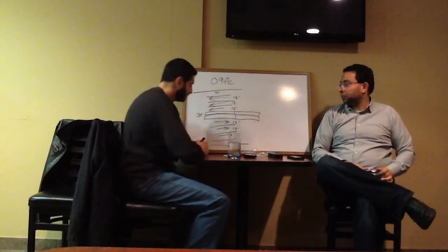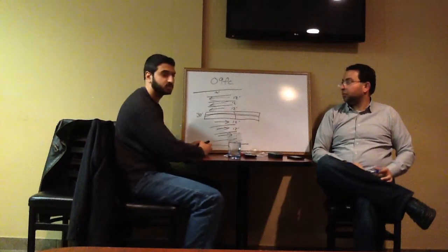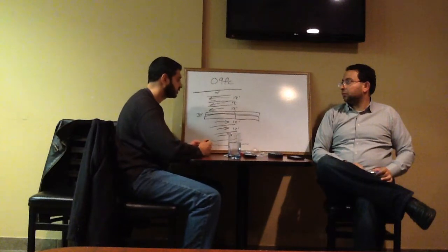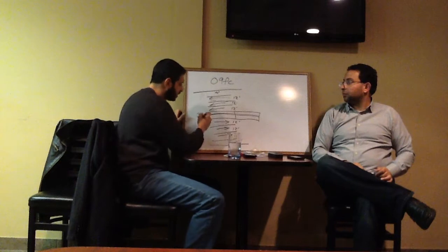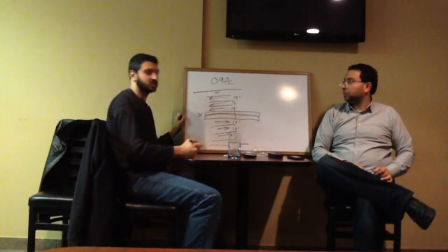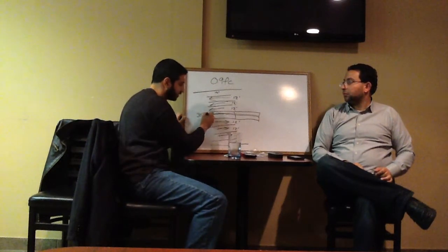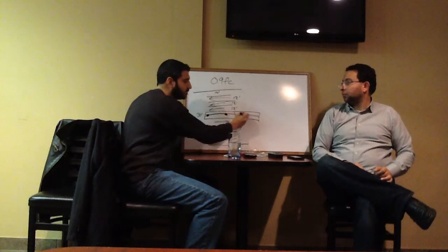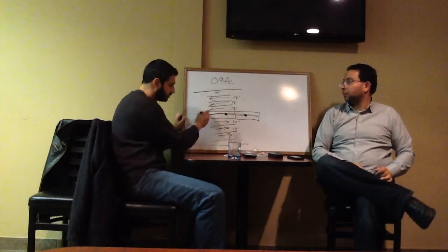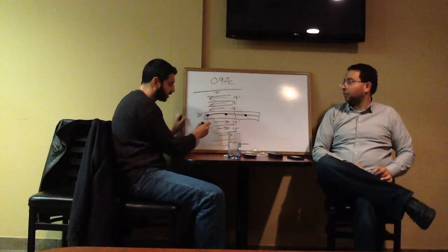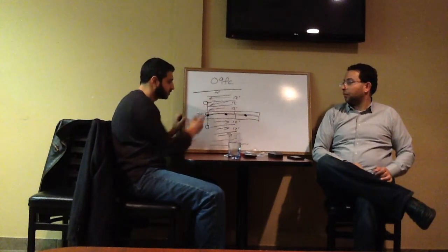Alright, so let's talk about the different kinds of layouts you can do for a roadway. There are what we call median mounted lights, so you can probably figure it out. The lights will be mounted in the median. So if you're gonna mount them here and you want to light both sides, you want a dual arm.